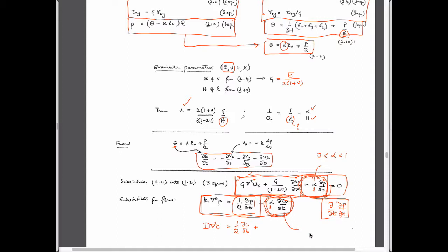And this, of course, here would be, since volume strain epsilon v is equal to strain in the x direction plus strain in the y direction, which is equal to change in displacement in the x direction with x plus change in displacement in the y direction with respect to y, then the time rate of change of this, strain rate, will be just this whole thing multiplied.